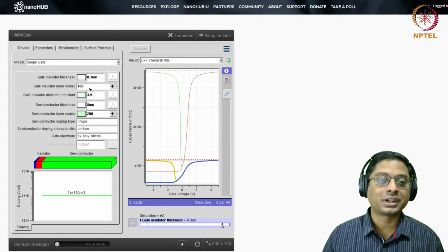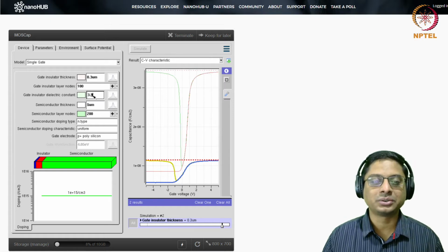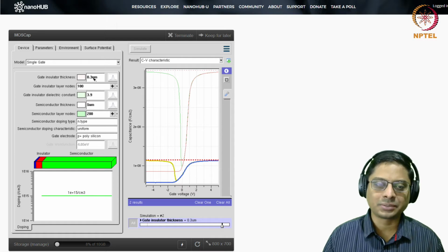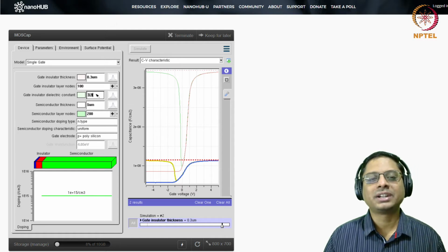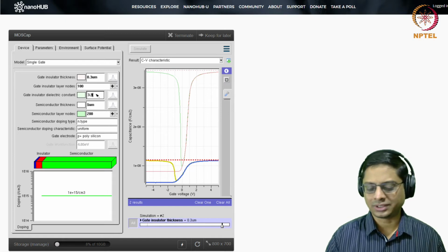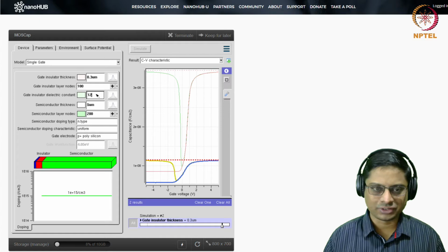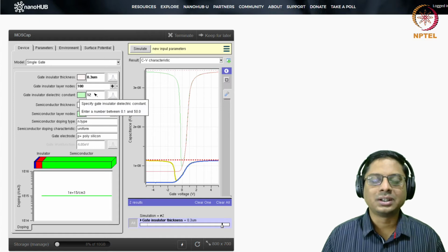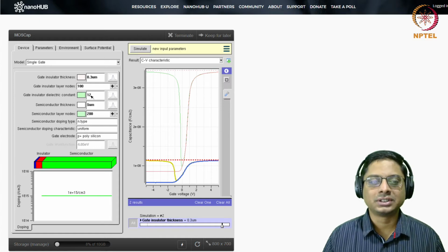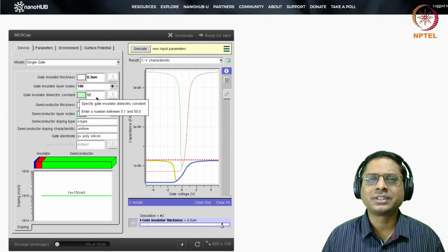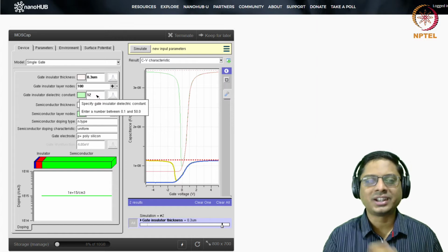You could also try, what happens if I change my dielectric constant? Okay, I'll stay at 0.3 micron, but I'll increase my dielectric constant 3 times. I'll make it 12, just arbitrarily. There are definitely some materials which have a dielectric constant of 12. By the way, you might ask: you said the dielectric constant of hafnium dioxide was 25 and silicon dioxide was 3.9, so how are we able to capture all the material properties with a single number?